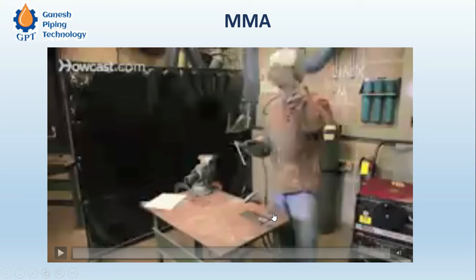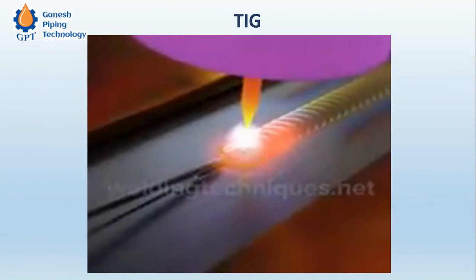Now we will go and see TIG welding, tungsten inert gas. Like in MMA, the arc was created by the gap struck between the base metal and the electrode itself, which is consumable. But here the electrode is non-consumable. It is a tungsten tip, and the filler metal is supplied separately by means of this wire, which we can see. The purpose of this tungsten arc is to create a constant, stable arc, and in the temperature of that arc the filler metal is deposited.